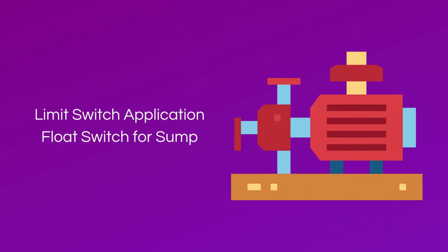It can also be used to activate a sump pump that pumps water out of a sump. For those that don't know what a sump is, it's a pit that collects liquid such as rainwater. It would be impractical and costly to run the sump pump all the time. Therefore, a limit switch that actuates a circuit that triggers the sump pump when water reaches a certain level is used. By using this switch, the sump pump only discharges water when necessary.